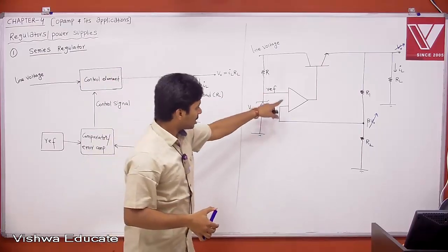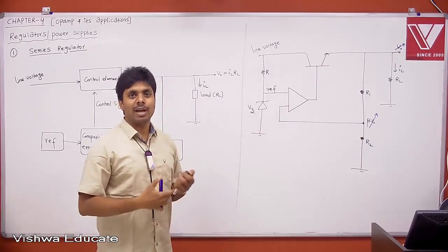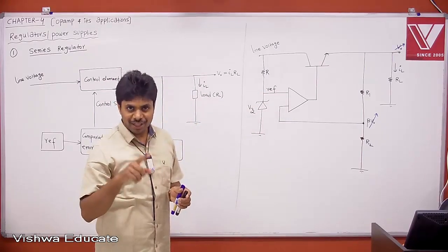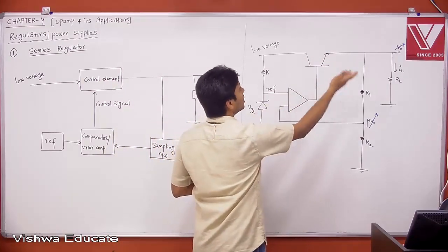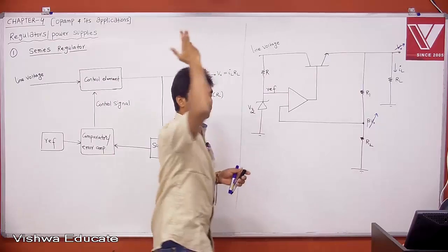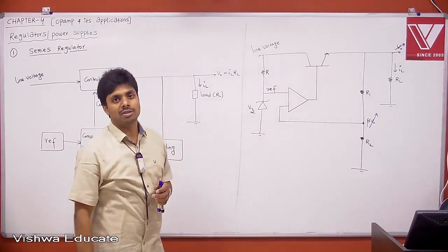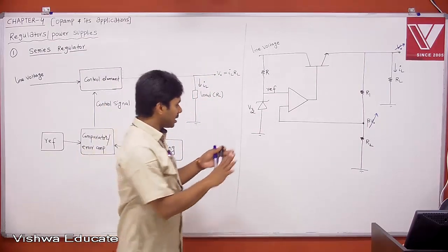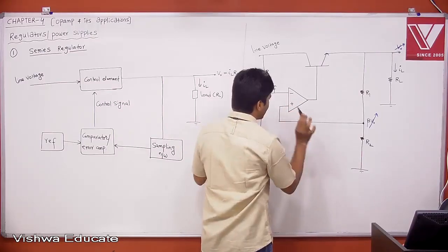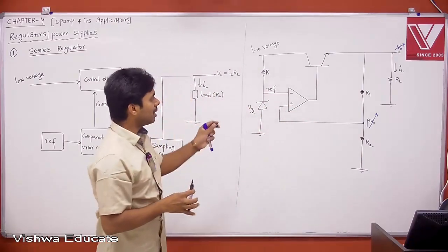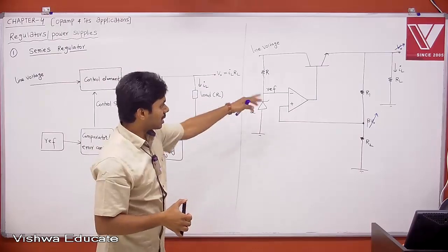If you put plus and minus the other way around, it may enter into positive feedback. If it is entering into positive feedback, and the output is increasing due to any reason, then the op amp will make it increase further, then your output voltage will go to the power supply or saturation voltages. Therefore, let us say we don't know, maybe for your understanding, let me take it as minus plus. Let's analyze, then let's see whether the terminal voltages, this is correct or not.